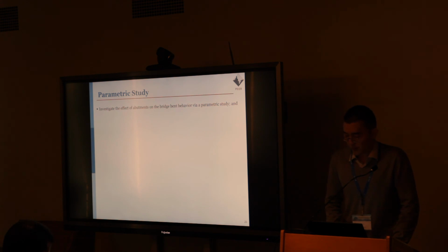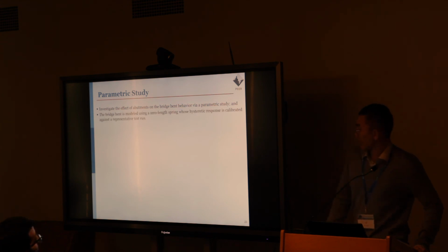And in order to explain the larger residual displacements at the end of the motion, a parametric study was considered to investigate the effect of the abutment on the behavior of the full bridge. To do this, the bridge bent is modeled using a zero-length spring whose hysteretic behavior is calibrated against